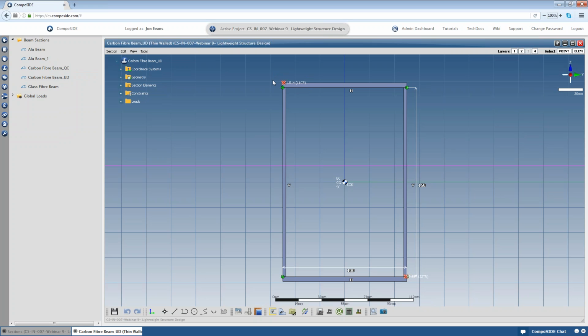I've also done a slightly different beam, so I've applied a different laminate to the top and bottom as I have to the sides. So I've got unidirectionals all at 0 in the top to use that compressive stress, and lots of 45, minus 45 in the shear webs, exactly the same as I did, compared the materials with shear strength.